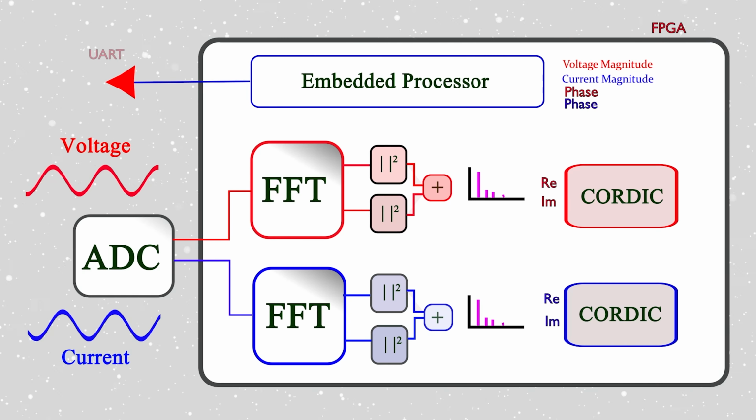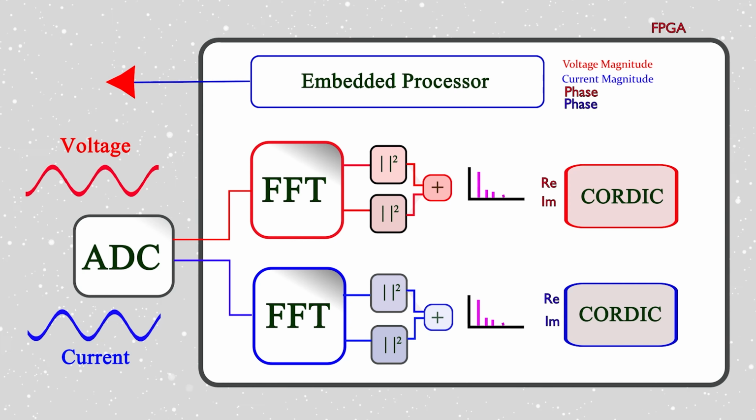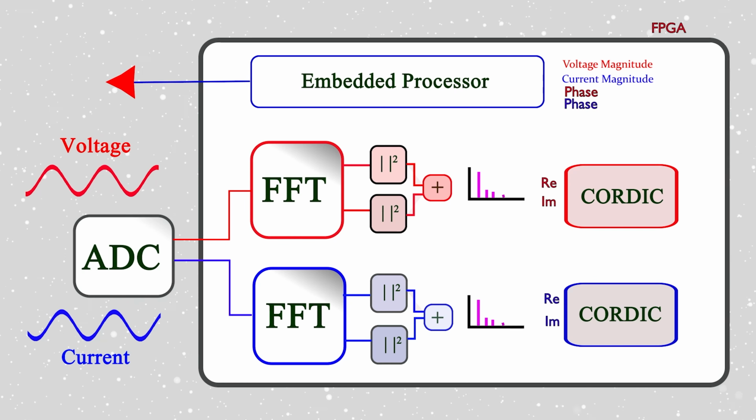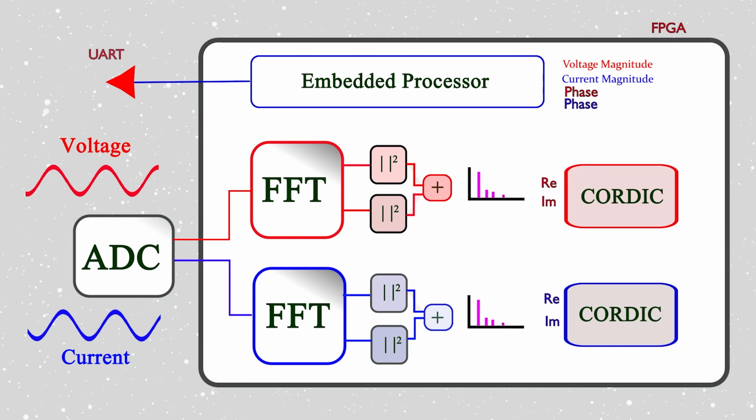Now, just one quick point here. Looking towards the next step, which is the FFT, we actually want the FFT to sample at the same rate as each sample is emerging from the A to D converter. And even though we have a cycle of 256 clock cycles, the actual sampling rate is once every 512 clock cycles, because we can only sample one channel every 2 cycles.